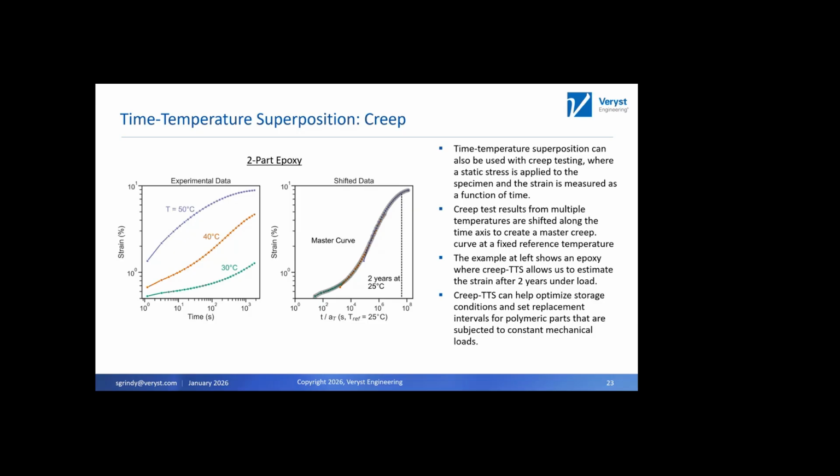at 40 degrees Celsius for 10 to the 4 seconds, it is equivalent, so it's probably going to be about, excuse me, 10 to the 4 seconds at 25 degrees Celsius is going to be about equivalent to measuring the deformation at 40 degrees Celsius for about 10 seconds or something like that. And so we're making the assumption that the self-similarity between these curves is descriptive of the physics of deformation of the material.